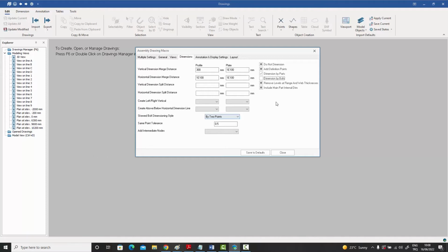And so the preferred way in steel is actually to dimension by bolts, because any tolerance mistake which you might have will be removed if the guys, when they're looking at the final assembly which has problems, actually locate that plate according to the bolts rather than the parts. And if that happens, then any 1 or 2 millimeter differences will be adjusted, because the bolts will at least be in the right place where they need to be.